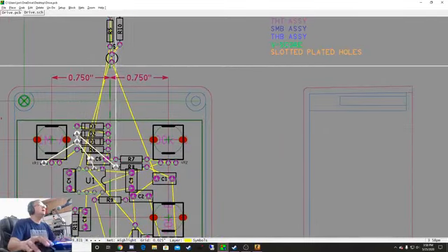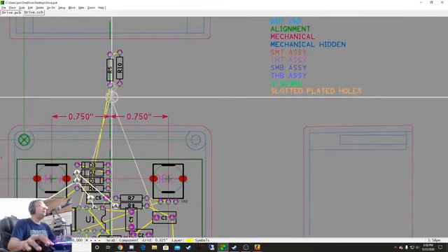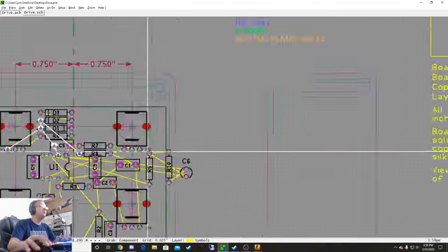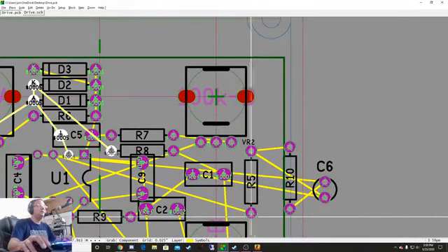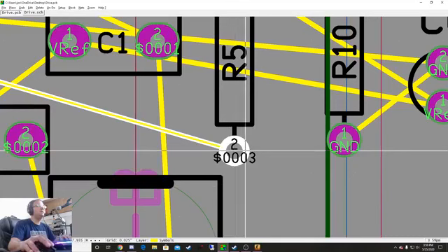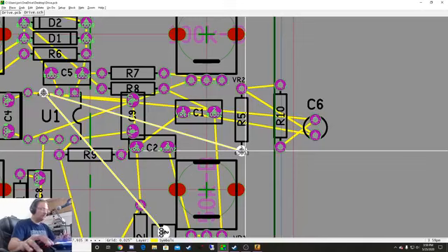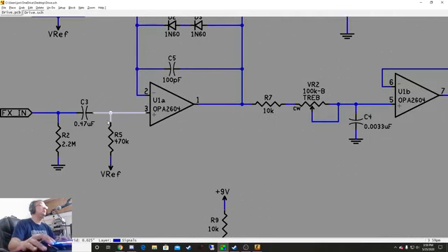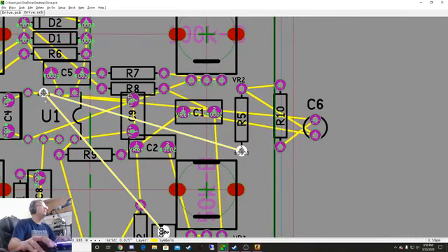And then we have a couple more resistors and a cap. So let's just kind of move these over here and get an idea what we're trying to do here. So these two parts, we got a VREF going to pin 3, or node 3. So see these right here, these node numbers are the signal name, the netlist name. That not only tells the schematic and circuit board what everything is, but when I'm looking for all the 3s as I'm routing things in my head, the netlists are doing the same thing for me.